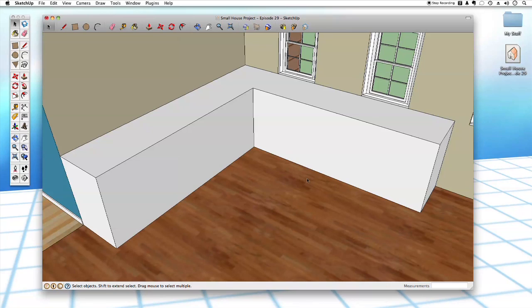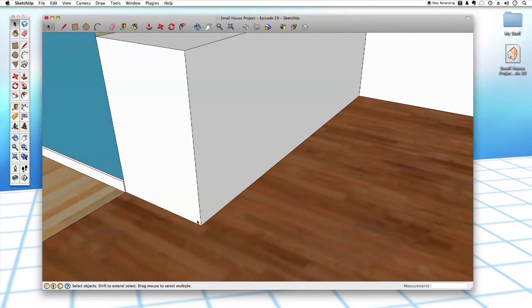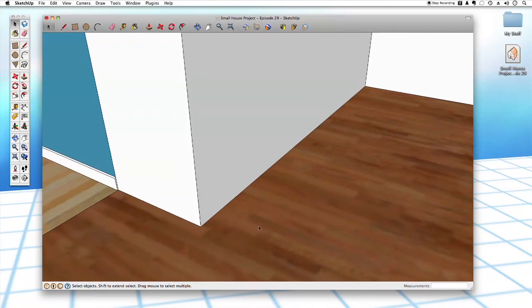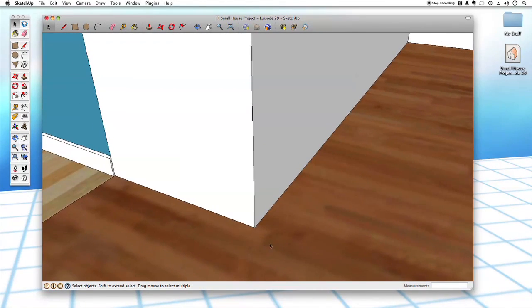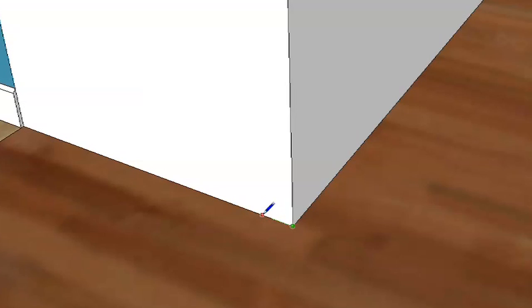Well, the cabinets are like solid. Most kitchen cabinets have a little notch cut out down here, and that's what I'm going to do next. I'm going to draw a quick little notch. Actually, I'll use the line tool for this. Let's say we want the notch to be 2 inches in. We have a little 2-inch line, and now I can extrude this up maybe 3 inches and out like that.